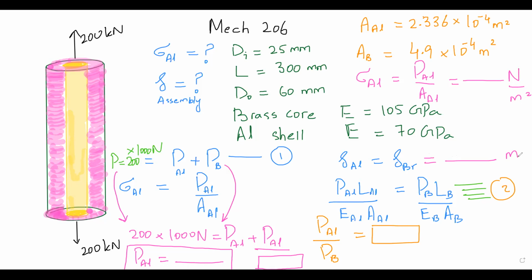For those of you who have just arrived, rigid end plates are at the end. I did not show that on the diagram. Kind of caps. So they are glued at the end, and then on those glued caps, I'm applying a load. So that load actually transfers to the aluminum and brass. So it's like somebody puts pressure here right now, or there are 2-3 guys who are sitting here and they are taking that load together. The one who is stronger will end up getting a bigger chunk of the applied load.